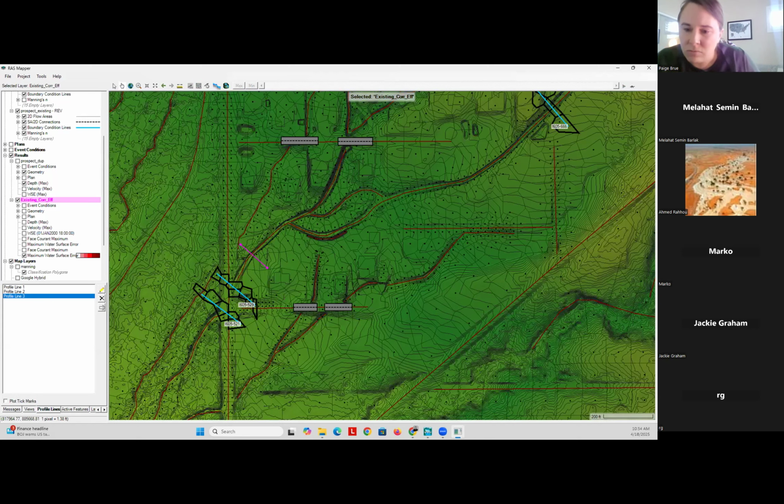I'm working on a flood risk assessment on a school located near the sea. Okay, near the sea. So a small suggestion I could make is to do a sensitivity analysis and determine how changing things like Manning's n affects the results, and make sure those parameters are very defensible.